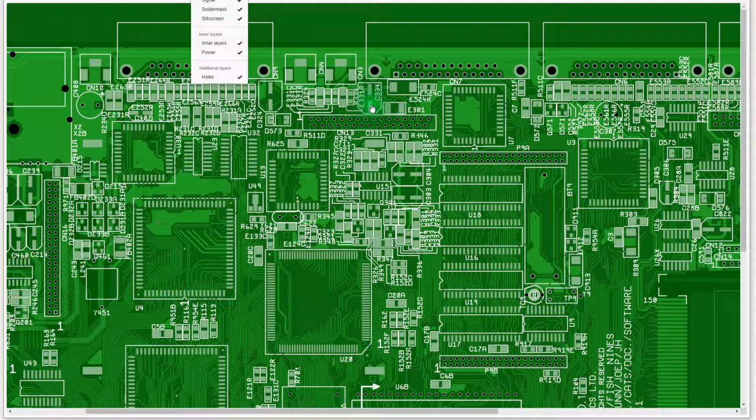There've been lots of forum entries talking about these electrolytic caps failing and causing audio issues. If this cap were to fail and leak and etch away the trace here or the trace here, that could potentially explain why I'm not getting audio out. The same thing goes for here. There's a little fine trace that comes off down here. I will probably start just by replacing these two caps.